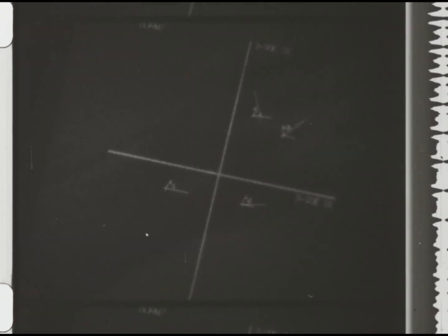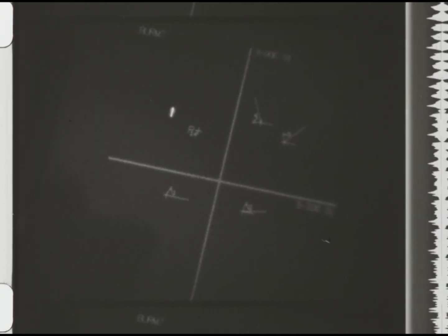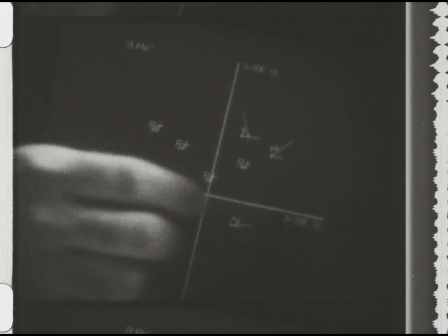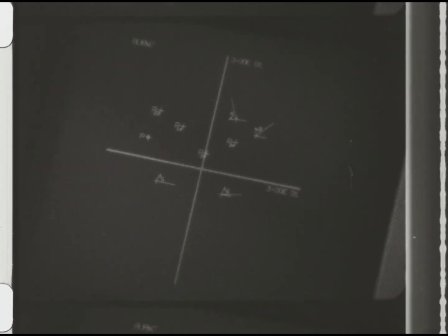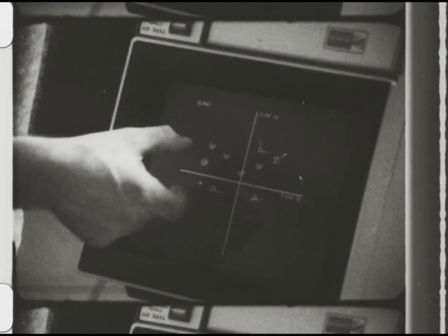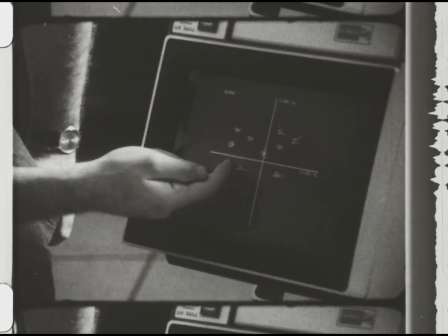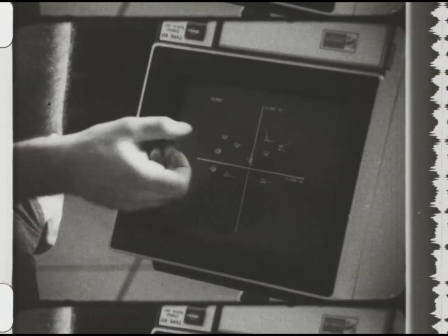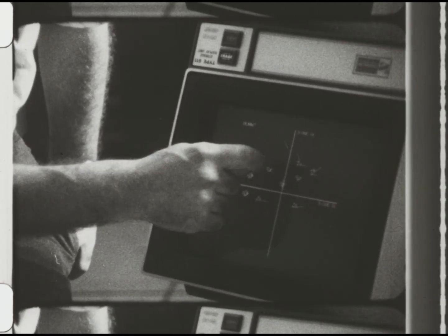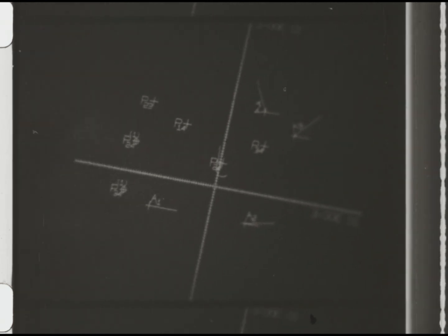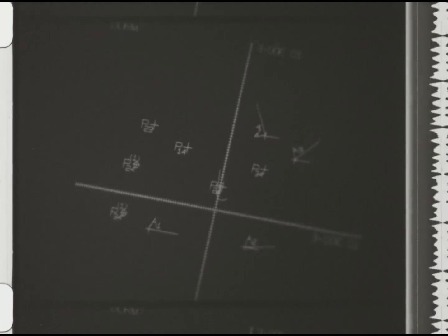For those design positions that Walt just happened to pick, the computer is now displaying some very useful design data. These are poles of rotation. As the body moved from one position to another, that motion could be accomplished by a simple rotation of the body about one of these poles. For instance, as the body goes from position 1 over to position 4, that motion could be accomplished by just rotating the body about this point P14. So these poles of rotation are poles corresponding to two positions of the moving body with respect to the fixed body.